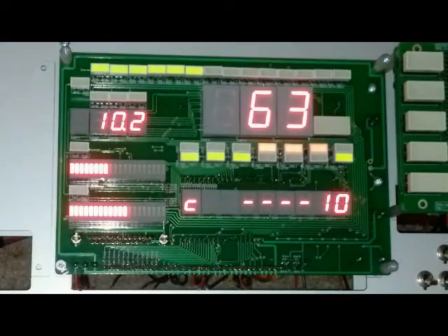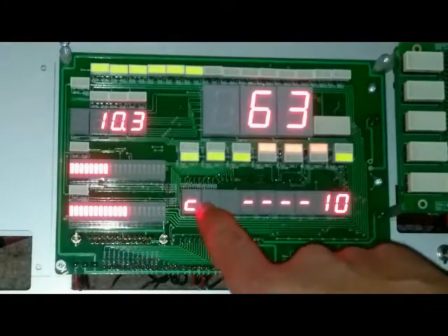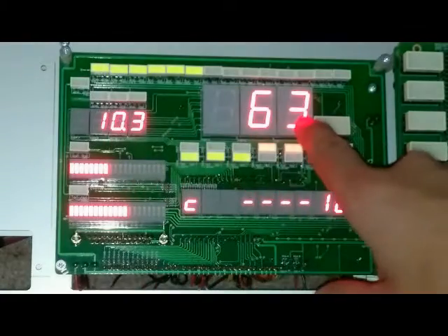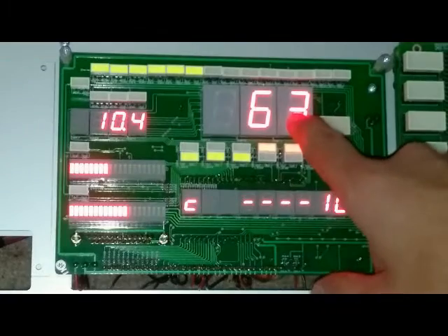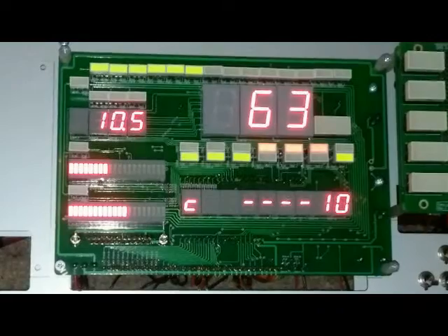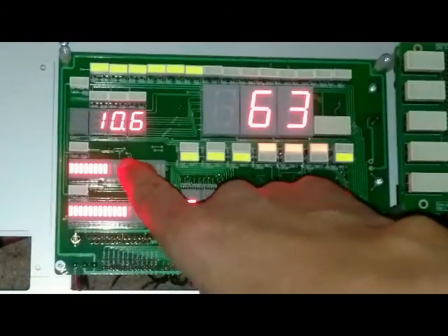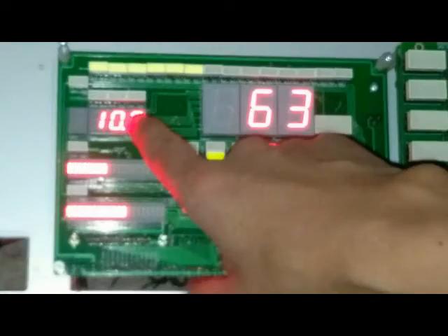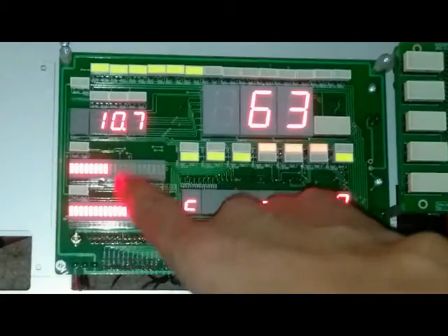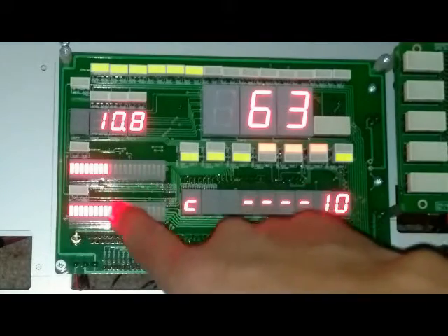Another thing that we can do from user options set by the computer is have the leading zeros on each of these displays showing or blanked. At the moment we have all the leading zeros blanked, so 63 miles per hour will show us 63. If we didn't have lead zero blanking on, that would show us 063, and so forth. Each of these bar gauges can also be selected to one of the 6 or 7 functions that the numeric display can be shown as. At the moment we have them shown as fuel and temperature, but when we hook up to the computer we can change the display of those as well.